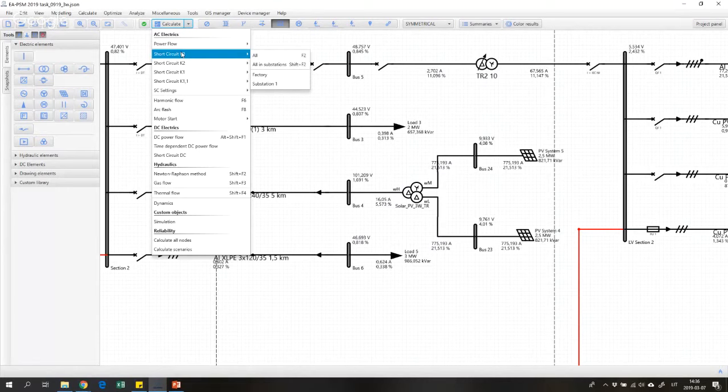So to summarize, first of all, we need to know how to calculate power flows, because it is important to evaluate how much your solar power plant will affect the network. Then we need to be capable of calculating short circuits, because according to short circuits we select protection equipment, and even the main equipment like cables, transformers, buses. Peak short circuit currents can cause mechanical forces, therefore all the insulators should be capable of withstanding those mechanical forces, and short circuit calculations allow us to get the required parameters for this kind of study.